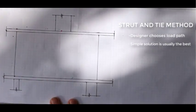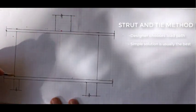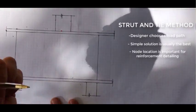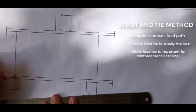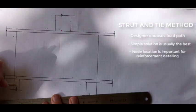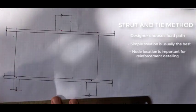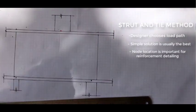So right here, we have the option of keeping the reinforcement inside the beam, inside the wall here, or we can choose the reinforcement to go into the slab. Depending on what's surrounding this area and the amount of reinforcement required, you can make that decision. But for this case, we will put the node here, in the center of the column. So the loads go from here to here, then back through the centroid of the column, and same for this case. Right now we're going to go in the slab. We're going to make sure we can fit the reinforcement in the slab with the reinforcement that's already meant to be in the slab.